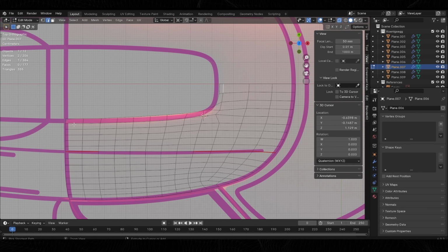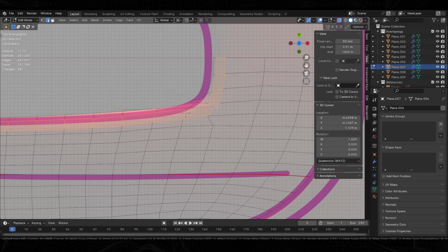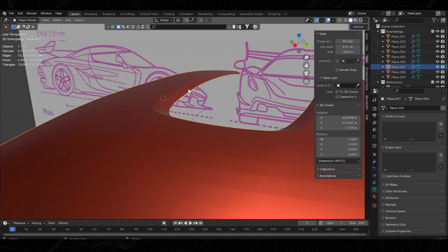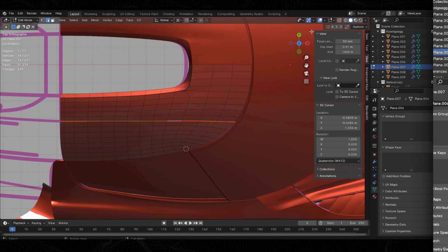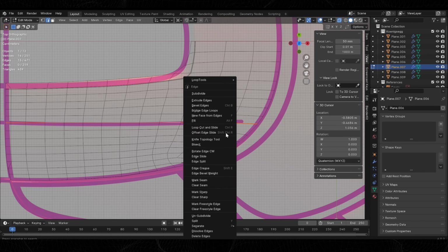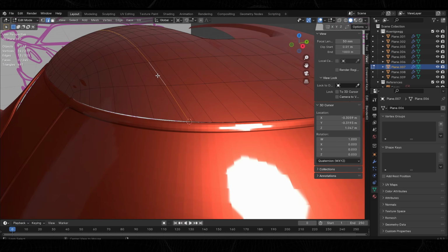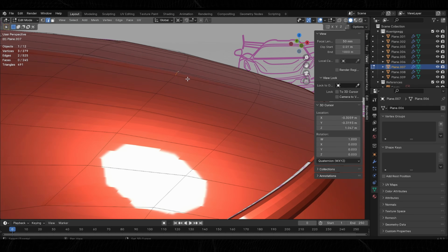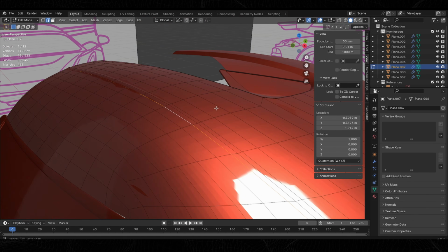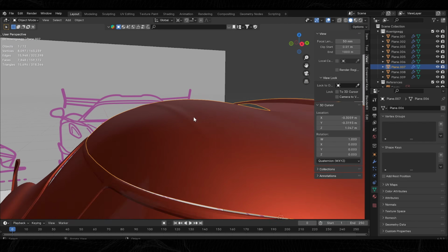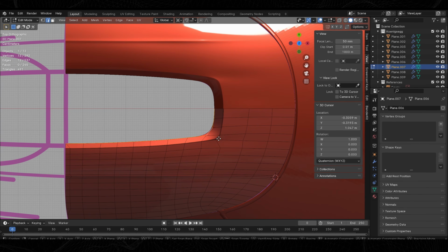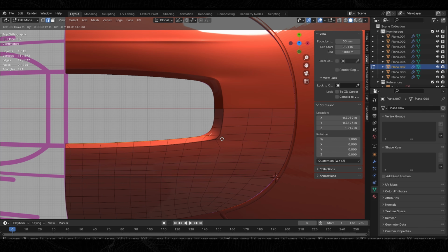When your roof is ready, make a 1-segment bevel here to create a soft but tight corner. Then create another one here and bring the vertices in the middle higher gradually to create this cool effect. And finally duplicate the vertices at the center of the roof.